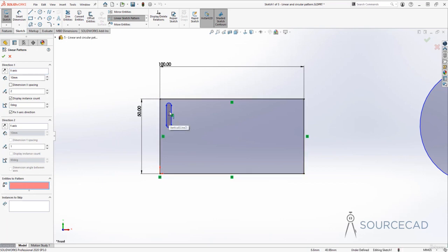Now I'll select this center line of the slot, and this will select the entire slot. Slot 1 is now selected, and now you can see 2 columns or 2 objects along x-axis and just 1 along y. Let's change number of objects to see it in a meaningful way. So I'll just increase number of objects along x-axis using this option. So that's number of instances or number of objects. You can just click on these arrows to increase or decrease it, or you can also add your own number. For example, I'll type 10 and I'll press the tab key.